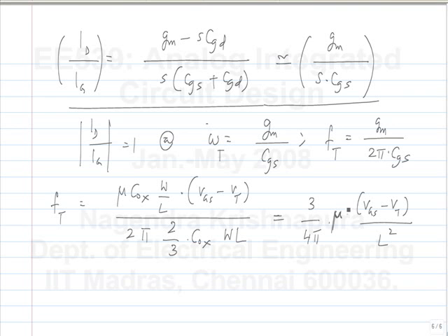So one quick example is, where would you want a small Vgs minus Vt? You want more swing. For the saturation voltage, you need to maintain a minimum of Vgs minus Vt across the drain and source, and you would like to keep that overhead to as small a value as possible. So in terms of swing limits, you would like to bias things with a small Vgs minus Vt.